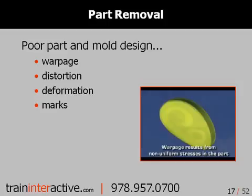In some cases, we've seen the use of air ejection by using poppet valves or porous steel to assist the ejection of thin-walled parts. When you use this type of system, the part will be ejected faster since the warm part is still soft and it blows off the core more easily.